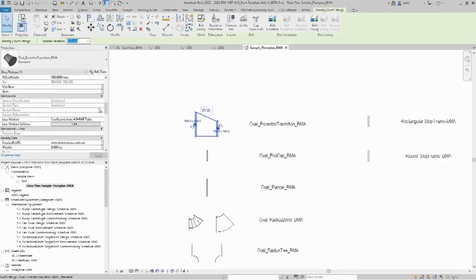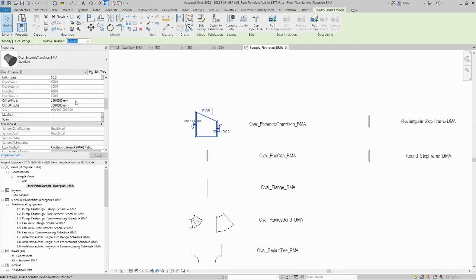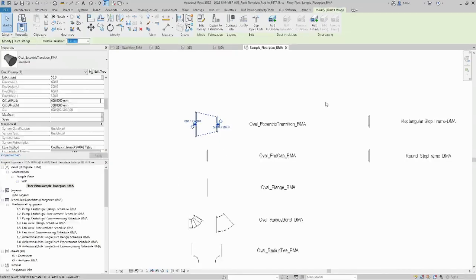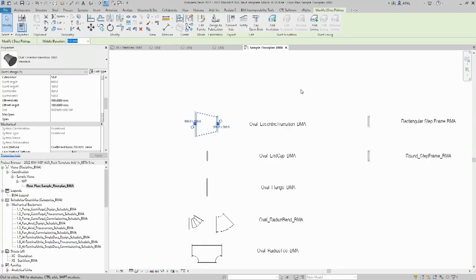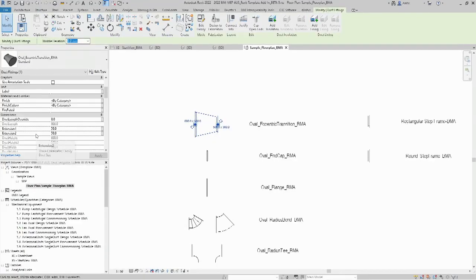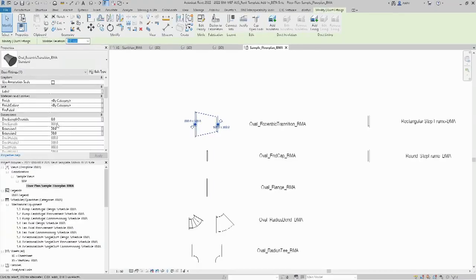Yeah, so this is one thing that we can do there. Maybe just go back to a concentric version of it. Another question that we get a lot is, I cannot change the length of that transition piece. Again, have a look at the properties. So there is the duct length, which is at the moment fixed to 800. All our transition pieces have that standard length of 800.